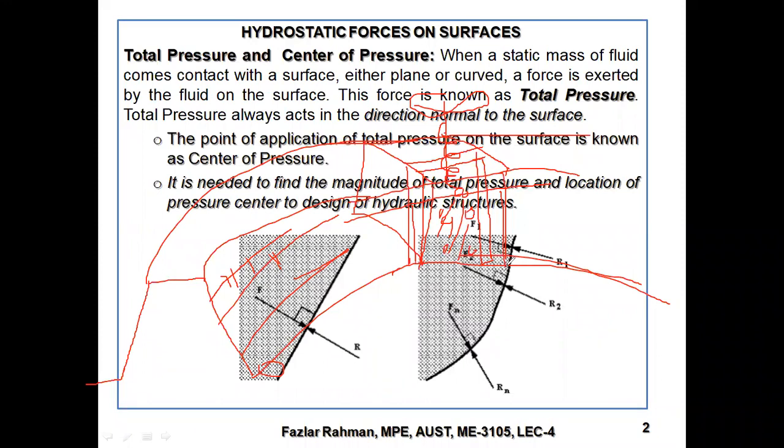So to figure that out, you need to know some rules about the pressure working on the plate. So what will be the resultant force? The resultant force you can figure out easily: F equals P into A, right? Pressure into area, because P equals F by A. Now, all the pressure, where it is working, that you need to figure out.